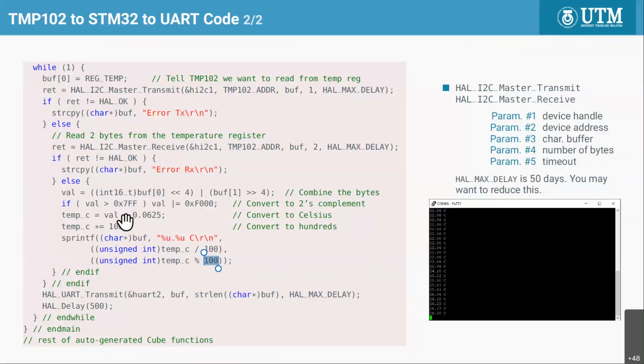So this one can be simplified if you decide, oh, I don't want fraction. I can save maybe 2 or 3 lines. Probably there's another way to make this simpler. Okay, so that is an example of how to use I2C. It's quite okay. If you want to try, you have to know the address, and that's it. And just make sure you check for errors.